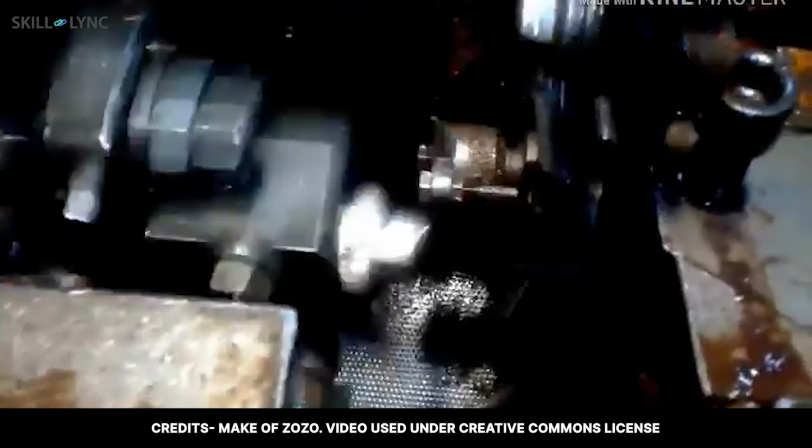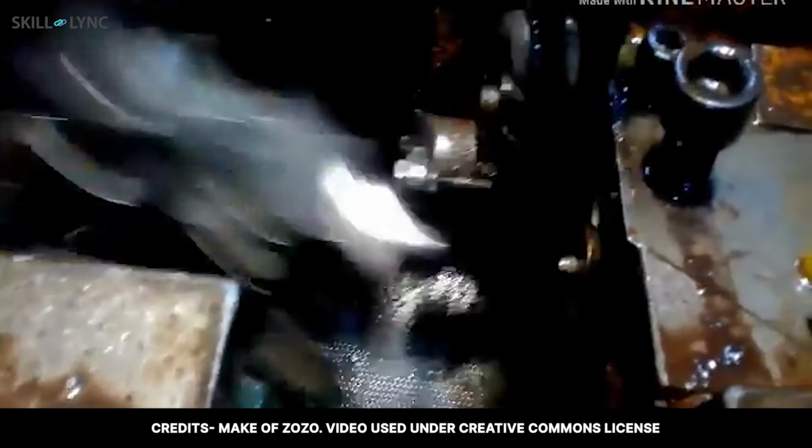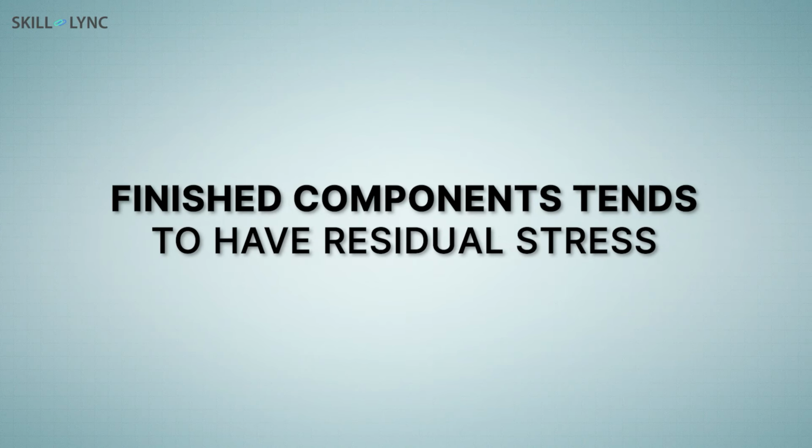The biggest advantage of the cold forging process is mass production. Because of this, the process is most commonly used to mass produce small components like screws, bolts, and nails. The process also requires very little finishing work on the end product. This also saves money to the manufacturer and is economical. However, this process cannot be used for complex shapes. There is also a chance that the finished component tends to have residual stress in it.